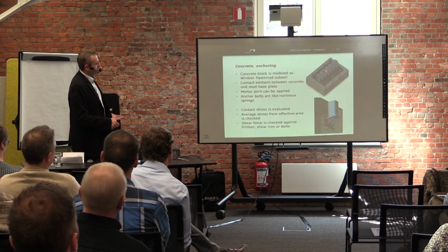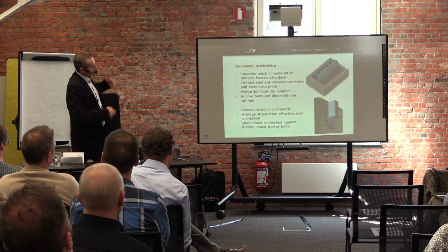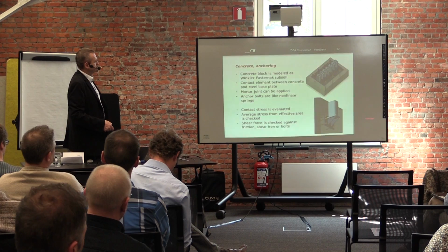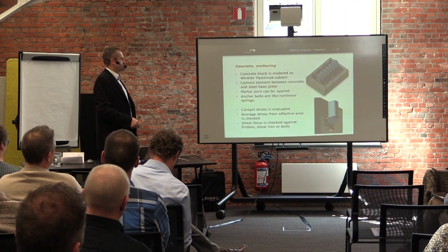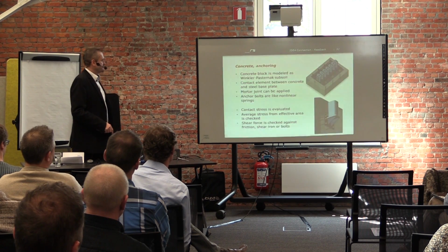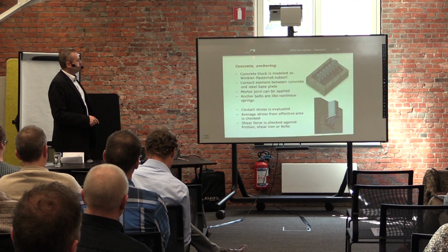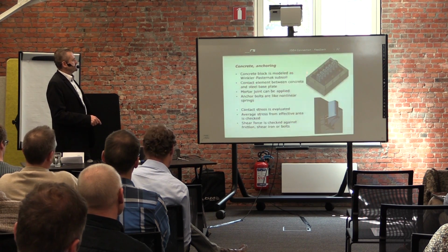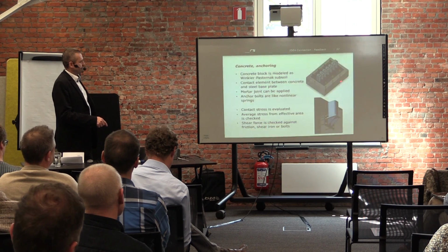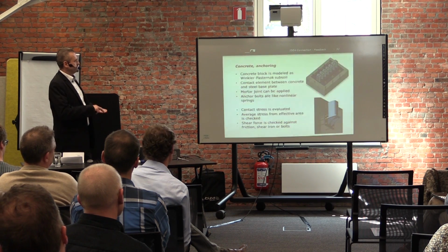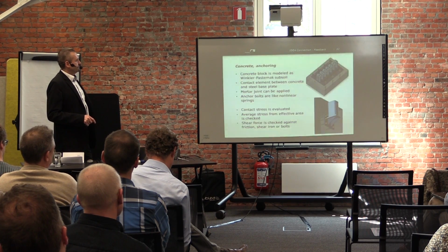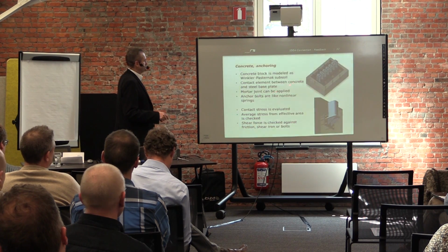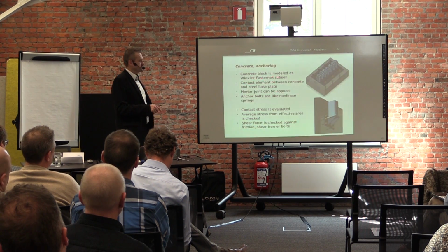I don't know what it is. This is some columns, many columns, and they do such things. This is the anchoring to the wall. It is thanks to this that we model also the concrete block under the base plate. This block is not modeled by finite elements, but we use Winkler-Pasternak subsoil.